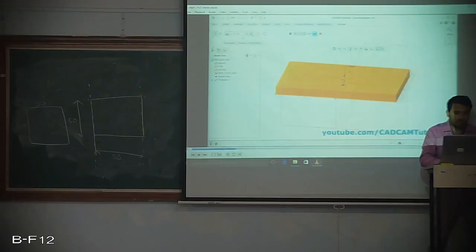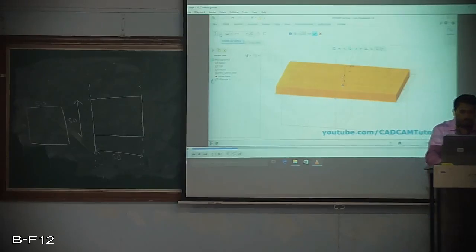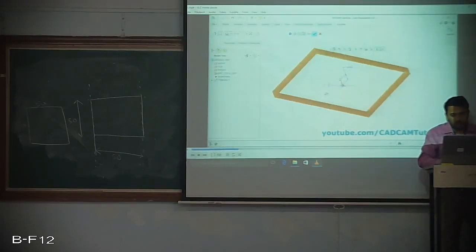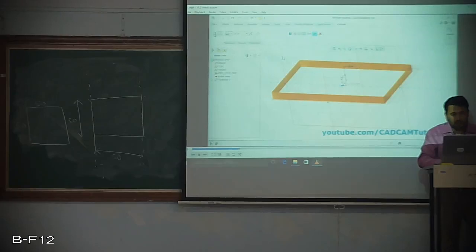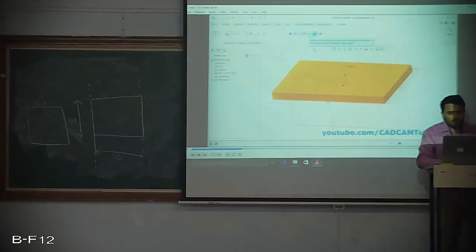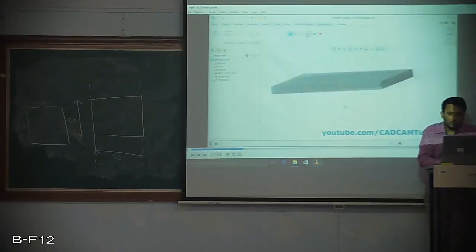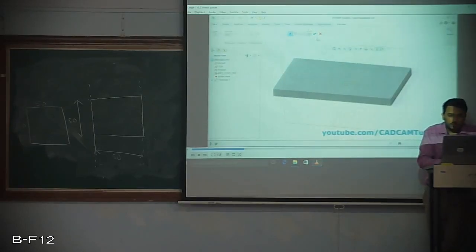So here there are some other commands. So if I use this, whether it is outside the sketch it will take 30 mm, inside the sketch it will take 30 mm. So I'll show what I mean by that. If I make the surface, then the entire part will become a surface. And again, if I want to make it a part, the entire drawing becomes a part. So this means the normal command. Click OK. If you want to cancel, you can cancel that.